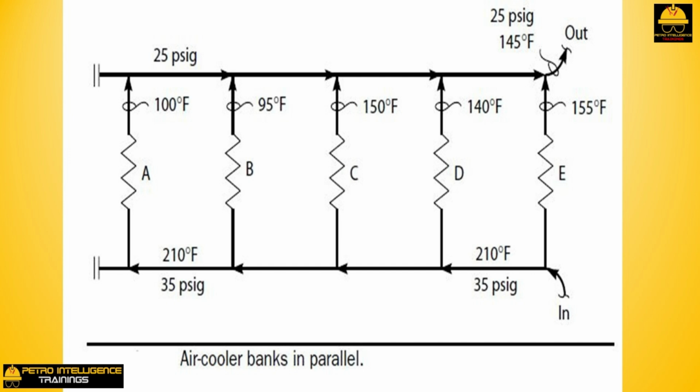Meanwhile, the air cooler bundles nearest the inlet header tend to see a greater and greater percentage of the total flow as the cooler bundles foul and plug. They tend to stay hot and clean, and those bundles farthest from the inlet header tend to run cool and dirty. It is a general principle of heat exchange that low flows tend to promote fouling and fouling promotes corrosion. The corroded, fouled heat exchanger surface retards flow and creates a vicious cycle. We will see this problem again in shell and tube heat exchangers in the next video.